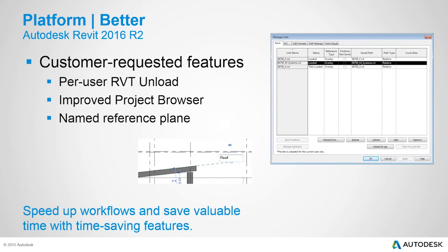It's another nice add-on. Named reference planes. As you know, when you put a reference plane across, over in the properties, you can give it a name. But now, when you place a reference plane, providing you've got your Release 2 installed, you can rename that or put a name to that reference plane right there on the canvas as you do it. It just makes life a bit quicker and a bit faster.